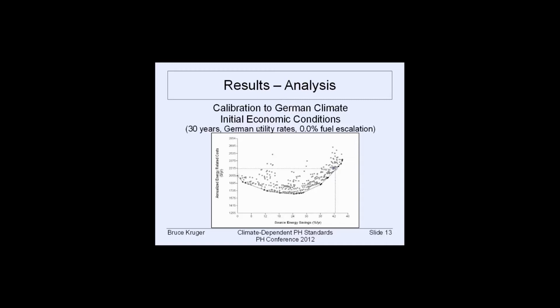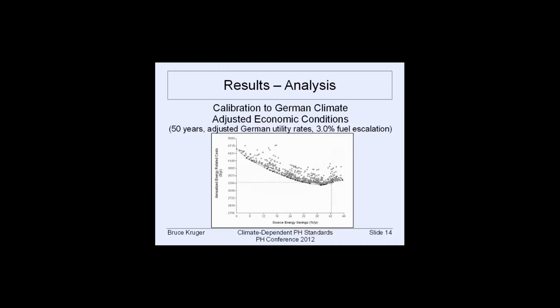That reminds me that in Germany, cooling demand is not really much of an issue. In this case it was really about meeting the heating demand, and then the cooling demand just happens automatically. So as I said before, the next part was to turn the dials on the economic conditions and look for a way to make the passive house design close to the minimum cost point.